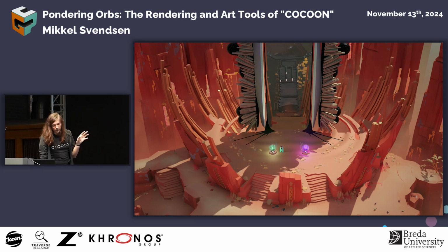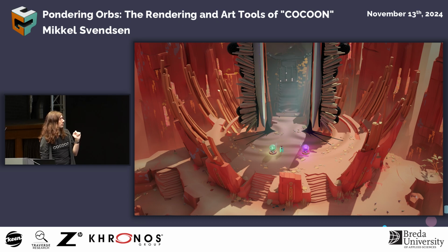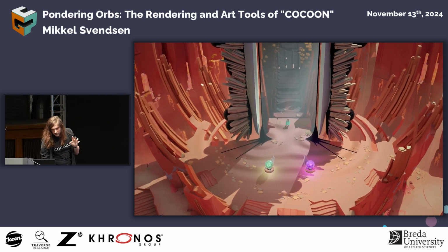The sun is removed on either side with just an invisible shadow caster. And on this side of the door, of course, the door itself is shadowing the sunlight away as well. So only that one light that we place between the two worlds is the thing that spills through for extra control. And it's simply duplicated on either side of the renderer. And to make sure that the door frame shadows it, there's just these two invisible shadow casters on either side. Isn't that funny? Anyway, so right then, let's walk through.